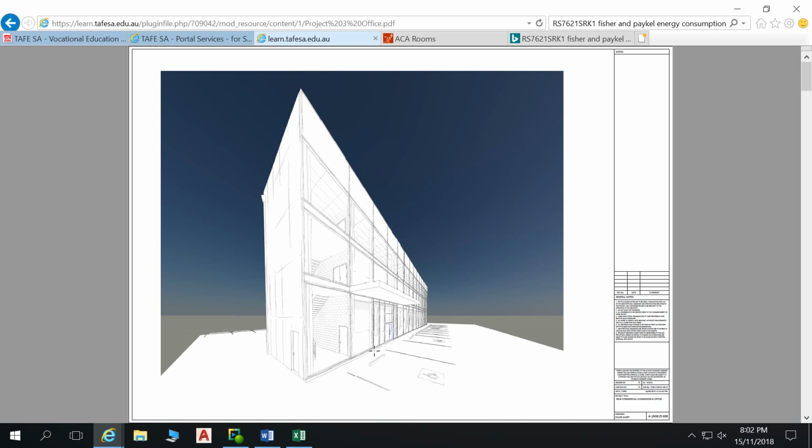So there's those sheets of Danpalon I was talking about. Okay. That go 30, 40 metres. Yeah. But they've got some purlins underneath them. So we've got the join in the sheeting on there where you have your little T-piece there. And so it's supported quite regularly. But I guess they'd probably be... I just wonder where the end joins are. They wouldn't have been bringing 30 or 40 metre sheets to site, would they?